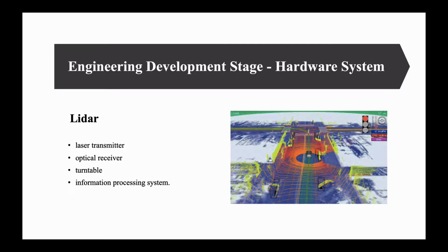digital elevation model. When the car encounters an obstacle, lidar sends a laser beam to the target. The laser turns the electric pulse into an optical pulse and emits it. The optical receiver then converts the reflected light pulse back into an electrical pulse and sends it into the display. Google, Uber, and other mainstream autonomous car research and development teams are using lidar as one of the sensors, which can be used with image recognition and other technologies to assist cars to determine road conditions.